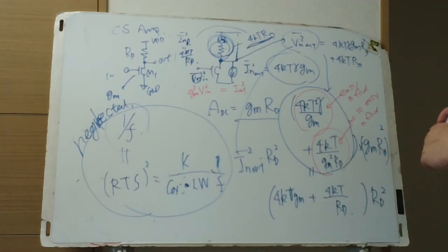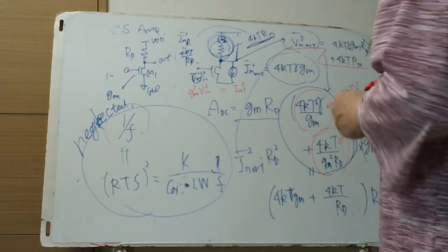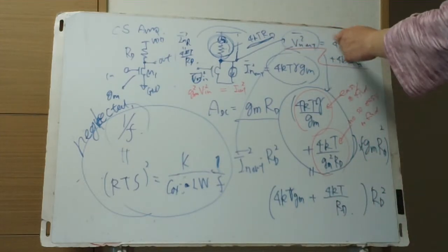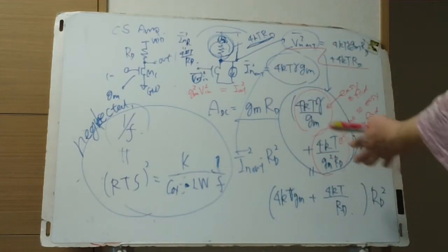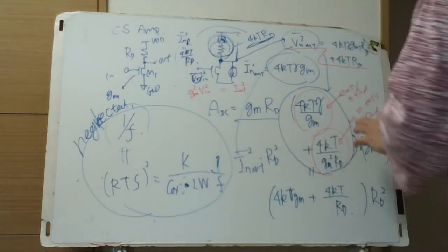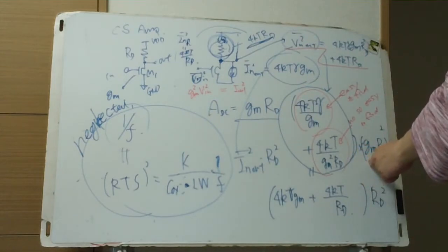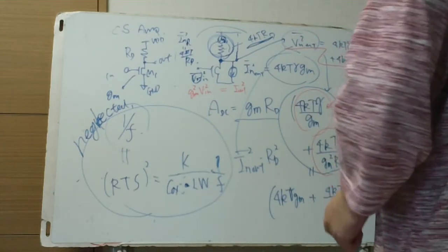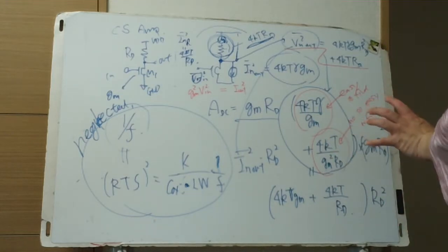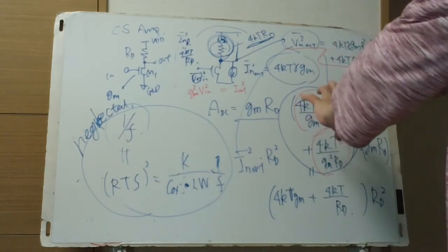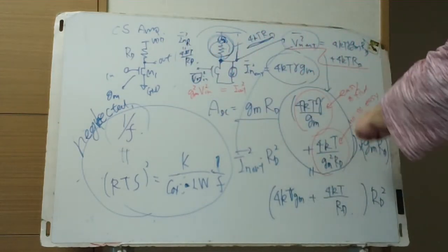So in this case, it's easy to find the voltage noise adapted to the output voltage noise, and using this transfer function, of course, in this 4-step procedure, this is 3 steps of this, step 4, and we can get the inversely input referred voltage noise.